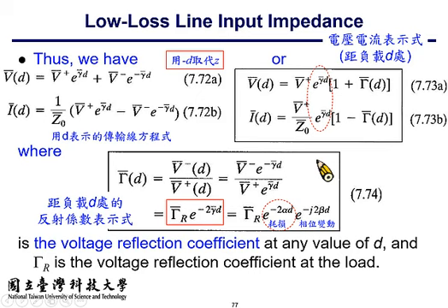At an operating frequency, you want the S11 level to be small, which suggests most of the input signal is radiated out from the antenna. However, for some poor design, you have S11 like this, which means only about 50% of the energy that goes into the antenna gets radiated, and the other half gets reflected back. So it's a lousy design.